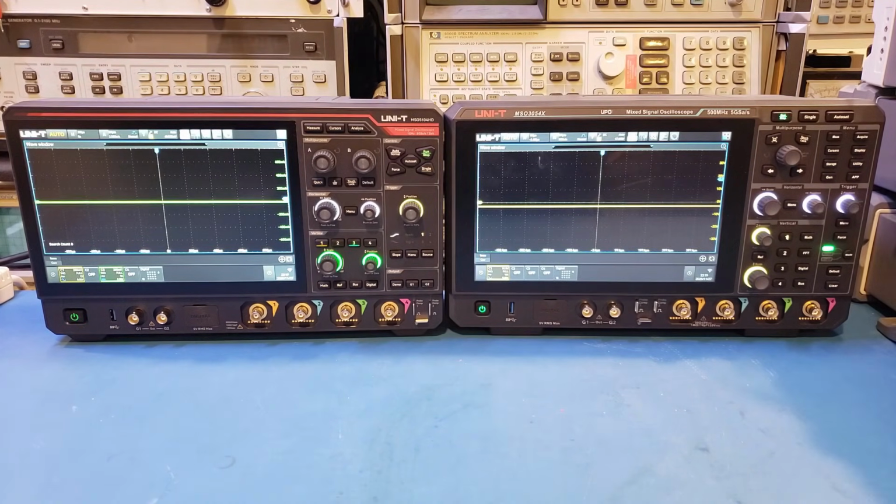Anyway, so what are some of the main advantages of a 12-bit scope as compared to an 8-bit one? While I still have the MSO3054X up here, let me actually show you that. The most obvious answer is that we now have more vertical resolution. Instead of representing the signal in 8 bits or 256 levels, now we have 4096 levels, so obviously you have more granularity. That is actually important when the captured signal has high dynamic range. And this is especially useful for doing analysis on rare signals captured via single shot. So let me demonstrate that.